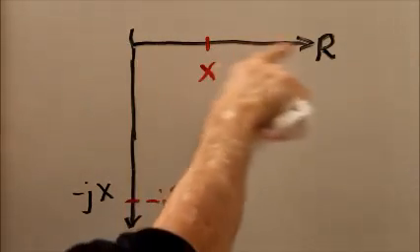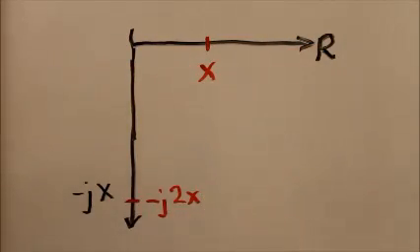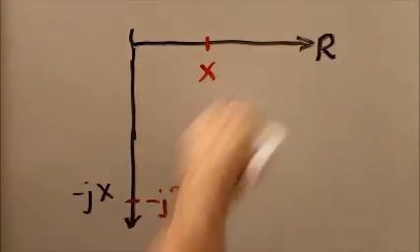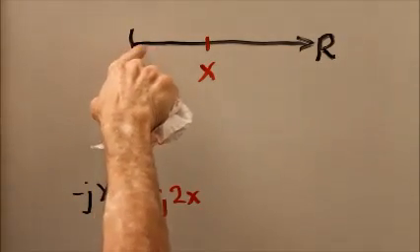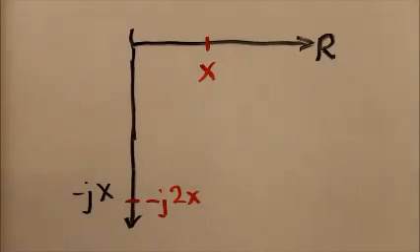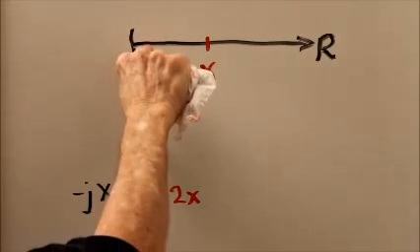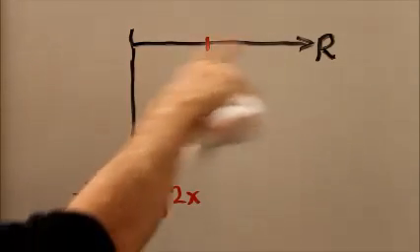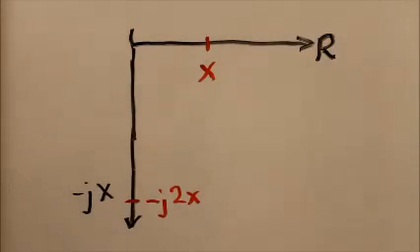If we draw the lower right-hand part of a complex impedance half plane like this, and we say that the increments are the same size along the axes, so that, say, 100 ohms on this axis might represent an inch, then J100 would represent an inch going that way, so the axes have the same sized increments.